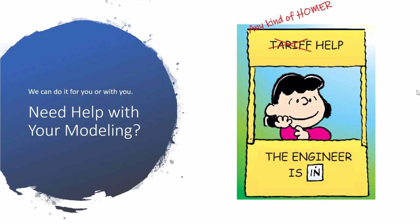Right, and that's based on both the throughput or the shelf life, depending on which battery model you use. There are different points at which it'll show that the battery needs to be replaced. That's why we have a couple of different battery models to capture different technology types. We have an idealized model, which is great for lithium ion, a kinetic model, which is great for lead acid, and our advanced storage module captures everything and is the most detailed of the models.